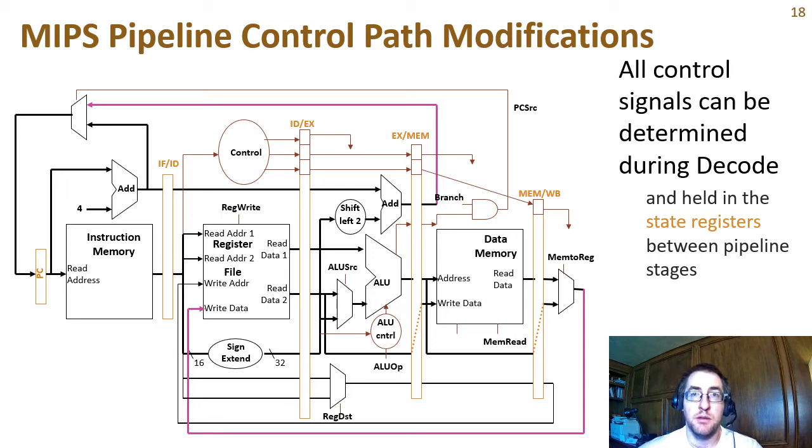So that by the end of the pipeline, the only signals we're left with are the ones that we need in the final stage, the mem write-back stage. And we indicate these buffers by the names of the two stages on either side of them. So we'll call the IFID interstage buffer the one between the IF stage and the ID stage.